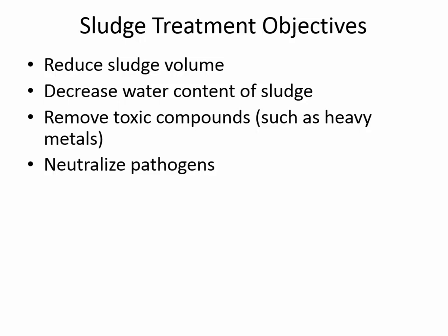You can, but the sludge solids will clog the membrane very quickly. And so, that's what we're trying to do, is find out some way to get the solids and the water separated. If we use progressively, increasingly small diameter pore sizes, then that can work. But if we take the sludge directly to ultrafiltration, then the issue becomes trying to get the membrane clean.